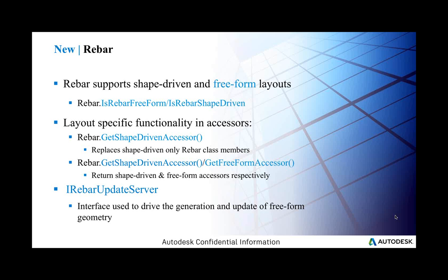So you can imagine how these two new pieces of functionality can be connected. A dynamic direct shape element can be dynamically updated by some functionality, and the IRebarUpdateServer can be used to react to the direct shape changes and update the rebar hosted by that direct shape.